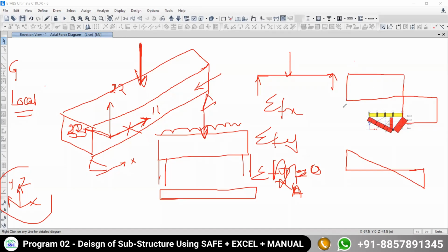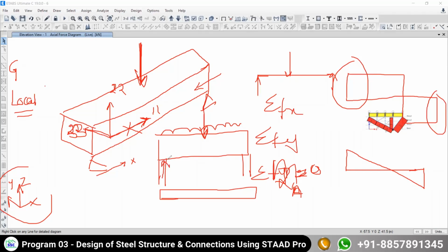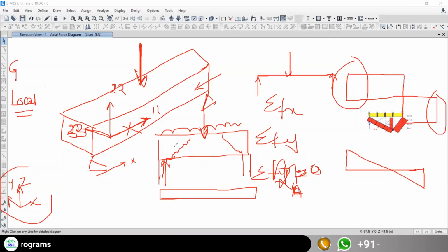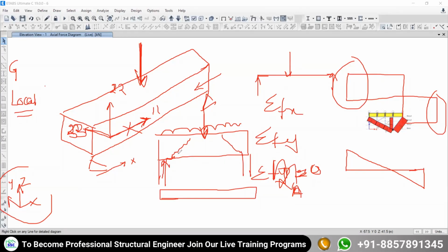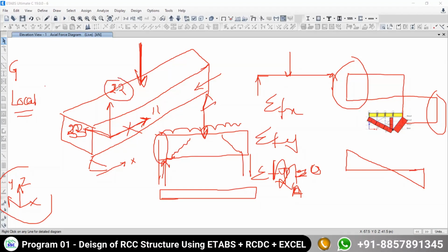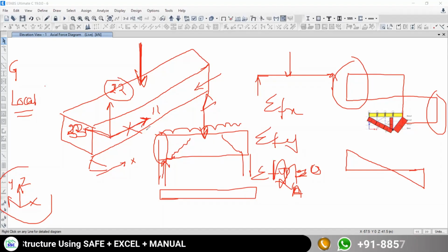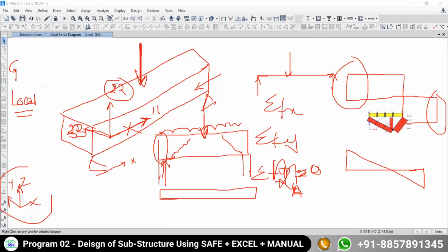It means that over the support, your shear force is very, very large. Due to this very large intensity of shear force, there will be the possibility of development of shear cracks in this direction. So what I would like to discuss is that the shear force is developing over the depth of your member. So your depth axis 2-2 is there. Whenever you want to look at how much shear force is coming to your beam, you need to look at the axis 2-2.